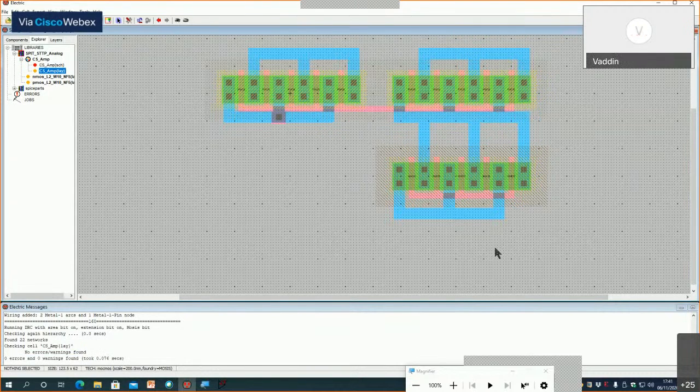So by this time, we have created the layout of the 2 PMOSFETs and the 1 NMOSFET in our circuit. And of course, certain optimizations are possible, but I am not paying attention to that. For example, you can bring the 2 transistors closer, no issue. I'm leaving it because that optimization takes time and comes with experience. So now the last component that is left is the resistor.